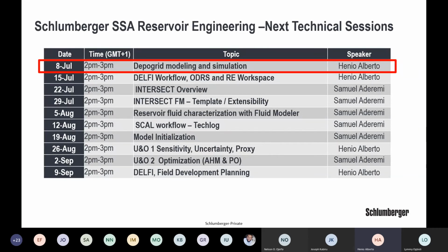And it may take a lot of time to set those up. While geoscreening quickly creates dummy parameters, dummy PVT, dummy relative permeability, because that does not impact the connectivity. You just want to assess the connectivity. So it quickly creates those parameters and allows you to simulate faster.